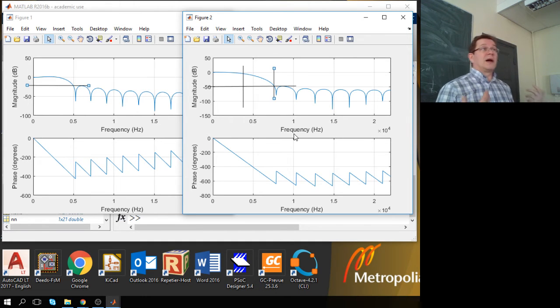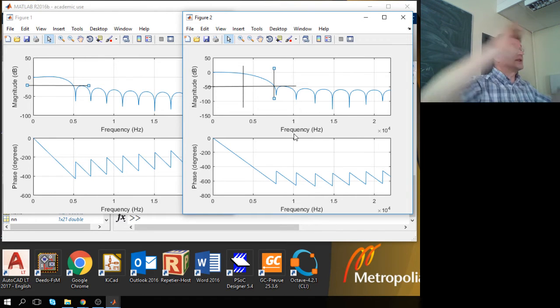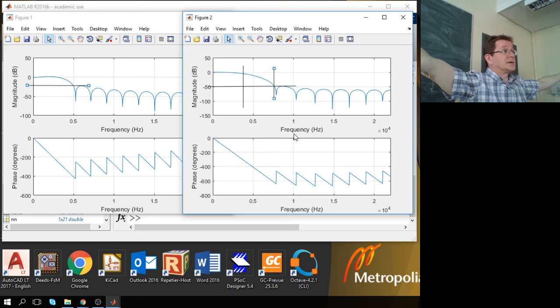Okay. So, but we are still missing one tweaking parameter. We can control the cutoff frequency by selecting the sinc, then the stop band attenuation by selecting the window shape, and then we can still increase the time, meaning take wider sample, to decrease the transition bandwidth.